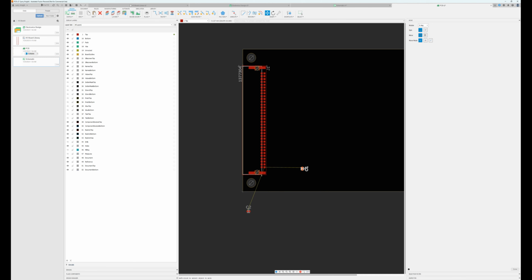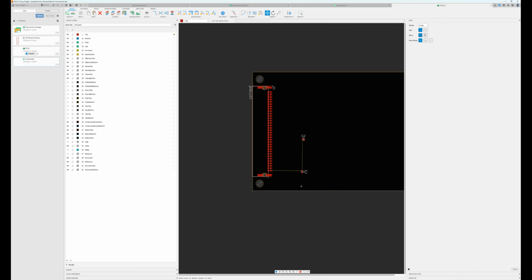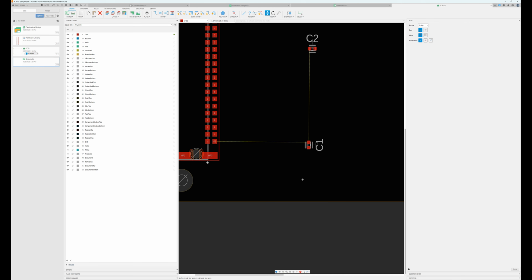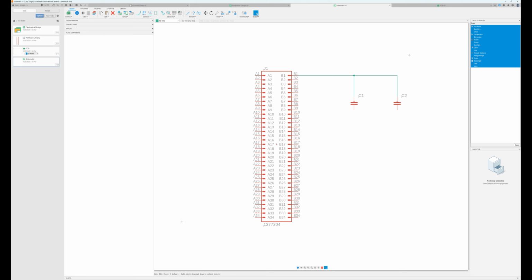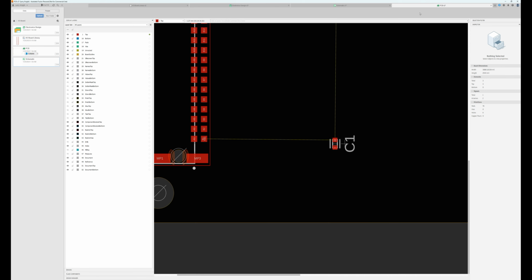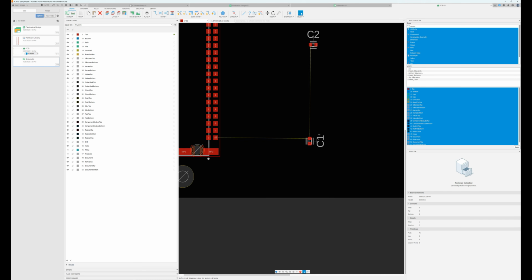All right, place that there and come down here, select that one, put this one up here like that, and then if you want it to align in a finer position, hold down the Alt key, click, and that places it. So now you have your trace from your schematic, represented over here in your PCB.